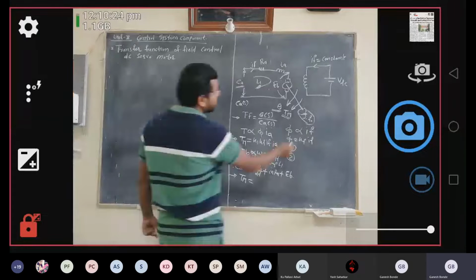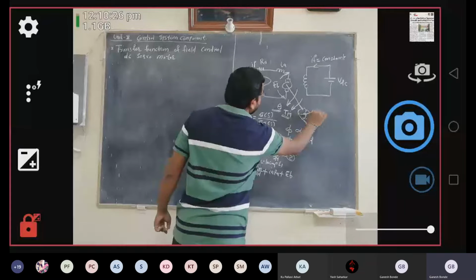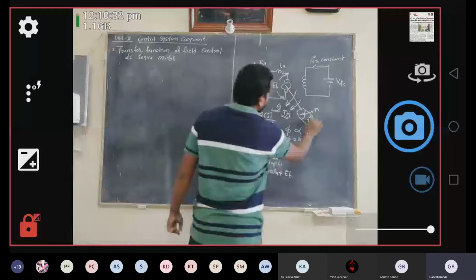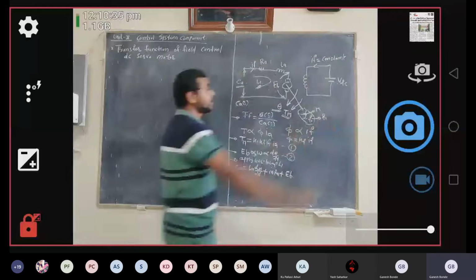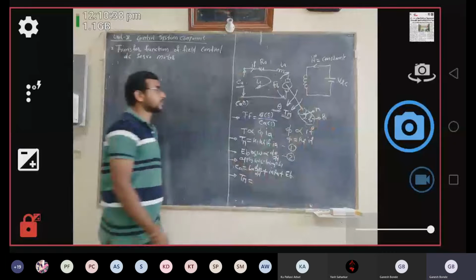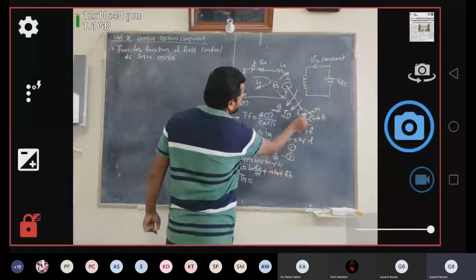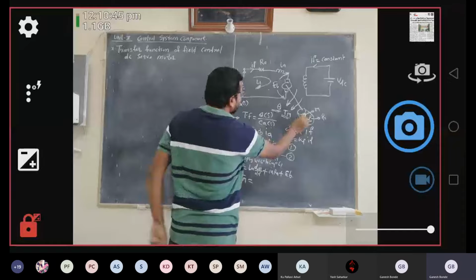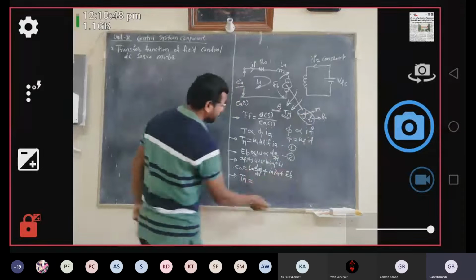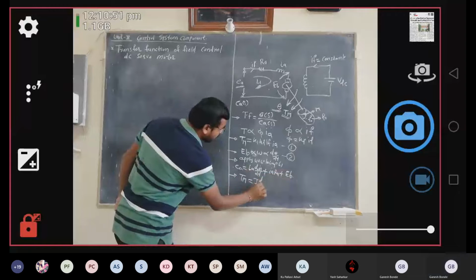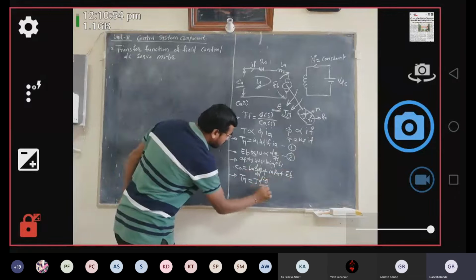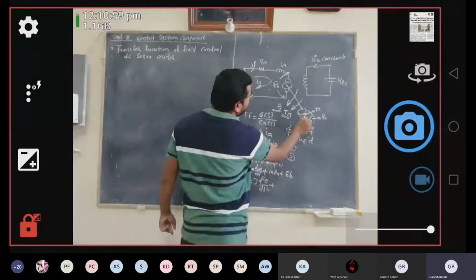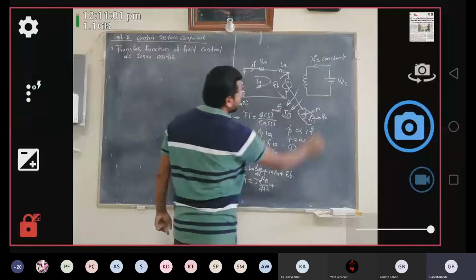So therefore this moment of inertia J is analogous to mass M in case of translational mechanical system. The frictional force F0 is also analogous to F0 in translational mechanical system. So what is the expression for torque which is acting because of this moment of inertia? It will be given by J d2 theta by dt square, that is the driving force required to drive this armature inertia.